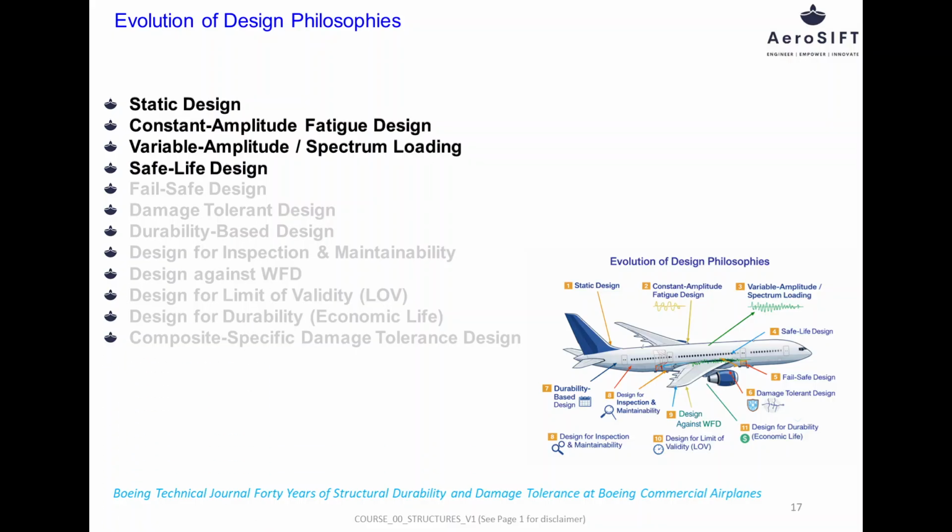In safe life design, the structure is designed to operate without developing cracks for a predetermined service life, after which it must be retired or replaced. No reliance is placed on inspections to maintain safety, as crack initiation is assumed to be unacceptable. While this philosophy offers high safety margins, it is conservative and often results in heavier structures and higher costs, making it unsuitable for large commercial aircraft structures.